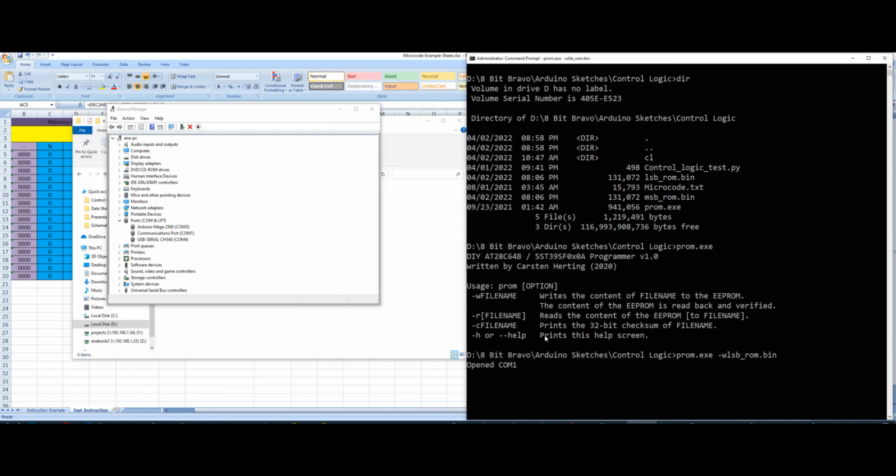So what I'm gonna do, I'm gonna abort that, and basically I'm gonna disable COM port. So you just write on your device manager, you click on the COM port and disable that, and then if you have any other devices connected and they're taking COM ports, you could either temporarily disable them, or you could unplug them.